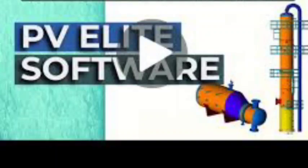No, but in PVLite API RP 2A is not there, no? That code is not there. Yeah, which is okay. So if that is not there, then you have to find an equivalent. You have to inform them we are in PVLite, it is not there. So we are going to calculate as per maybe the civil code, whichever is applicable or frequently used. So you have to inform them.